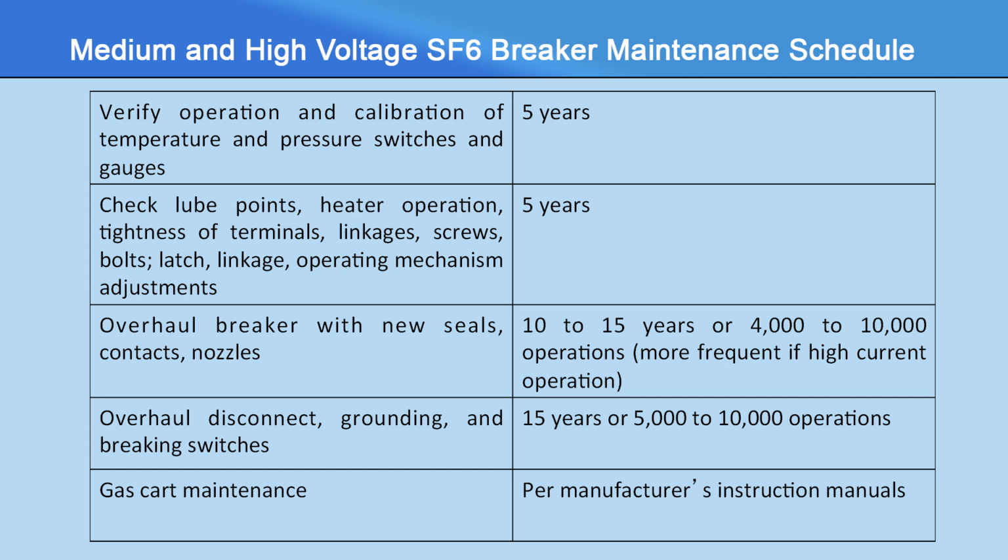Next is check lubrication points, heater operation, tightness of terminals, linkages, screws, bolts, latch, linkage, operating mechanism adjustments, which is performed every 5 years.